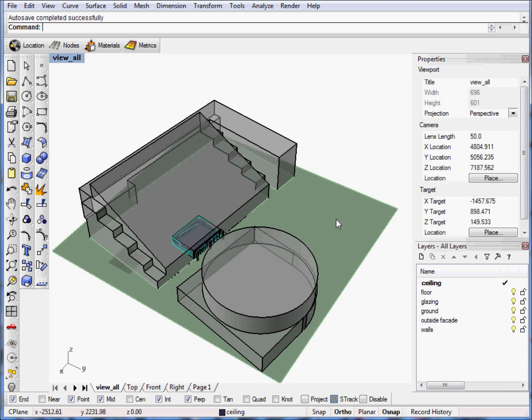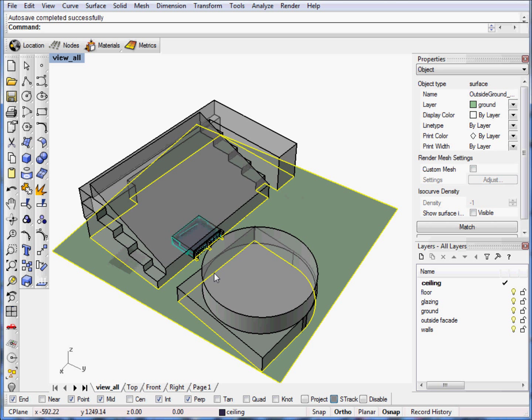It's important whenever you're modeling geometry for analysis with DIVA daylighting that you include a ground plane. And it's also important that you don't have coincident or coplanar planes. In order to prevent the ground from being coplanar with our floor, we've cut out the base of each of the buildings from the ground plane. You can also just offset it a couple feet so that they're not touching. But it's important to have a ground plane always in your model when you're doing daylight analysis.